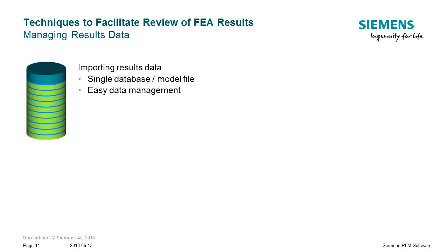FEMAP offers a lot of flexibility in accessing results data post-analysis. It is possible to load all the results into the FEMAP model database, which maintains a single file containing both modeling and results data. When you import results created by the solver into the FEMAP model database, the database itself obviously increases in size and ends up consisting of the original model data, the solver created results data, and some further address data to aid results data access. Import times can be significant for large results files, and the data can only be accessed through the single database. However, data management with this option is simpler.